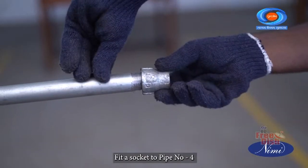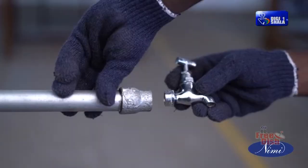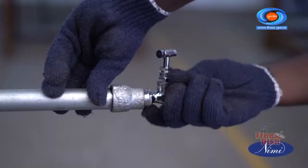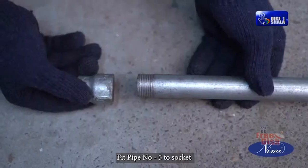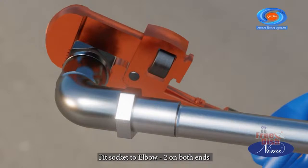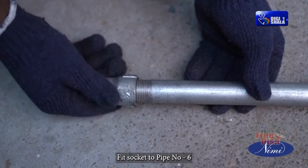Fit a socket to pipe number 4. Fit bibcock to socket. Fit pipe number 5 to T2. Fit pipe number 5 to socket. Fit socket to elbow 2 on both ends. Fit socket to pipe number 6.